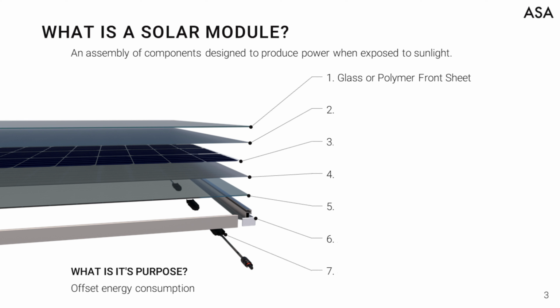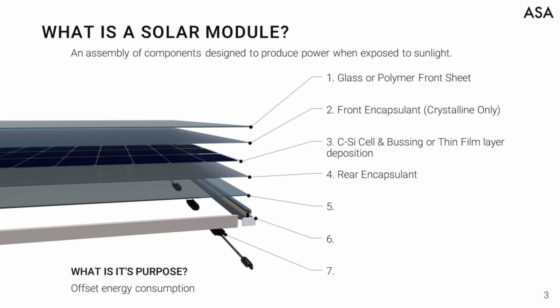Traditionally, front sheets are 2 to 4 millimeters in thickness and made with tempered glass. A front sheet's thickness enables impact protection at the cost of weight and efficiency. All solar modules feature solar cells. Those solar cells can either be deposited on glass directly or suspended within a laminate between two layers of encapsulant, as seen here. It is important to note that the addition of solar cell technology does not make architectural glass weaker. If anything, it may achieve greater strength because of the requirement to add an encapsulant to form a laminate.